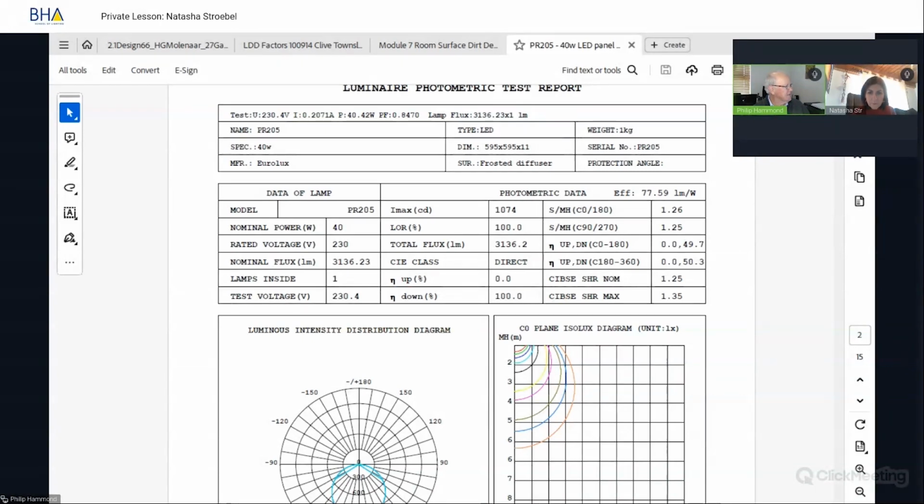And then on this side, it gives you surface to mounting height ratio, all right, in the different angles that you're looking at. So one lot of angles is length and the other is sideways. And then CIBSE is the Chartered Institution of Building Services Engineers, right? It's an international body, and they give you surface to mounting height ratios as well. So they are nominal, all right?